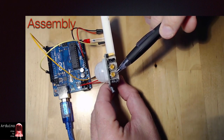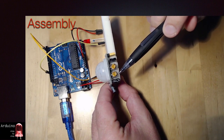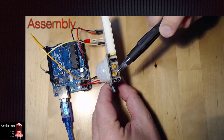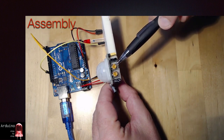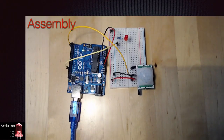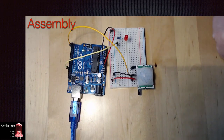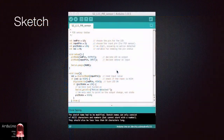Notice that there are two yellow knobs on the side of the sensor. One of them can be used to calibrate the sensitivity of the sensor, and the other one the amount of time that the sensor will remain at a high state after it detects motion. There you go, the sketch was uploaded. Now the sensor can detect my body as a source of heat and turns the LED on. Done with the assembly. Let's have a look at the sketch now.